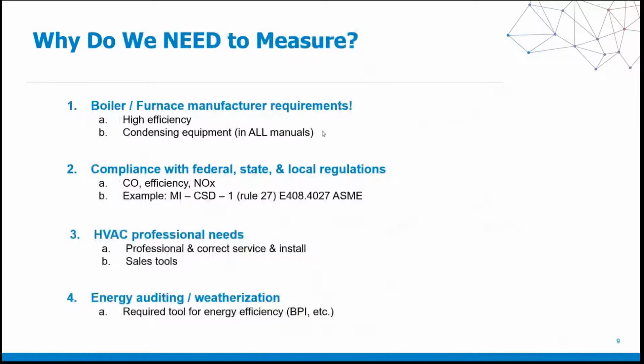Now, when it comes to why do we need to measure, there's 4 factors here. The first being that the boiler and furnace manufacturers want you to test. It's a requirement, as I just went over when I showed you a slide of the manual. They want you to test. Again, they've passed the liability onto your hands. It's up to you to set that piece of equipment up correctly. Not only that, it's up to you to test it when you're out there for any kind of service or maintenance visit.